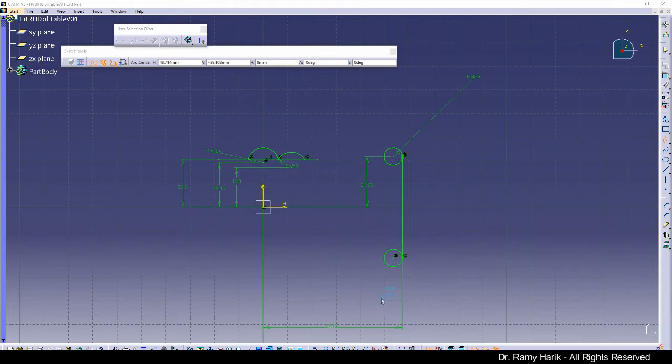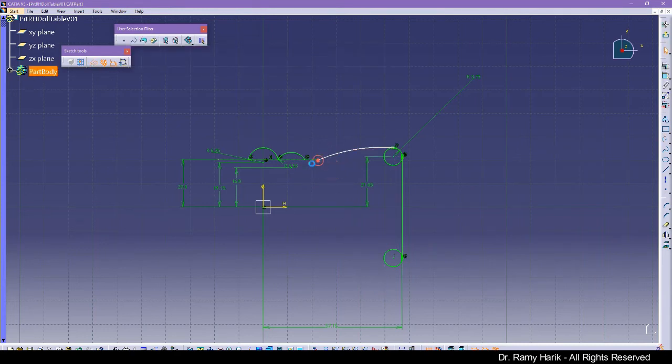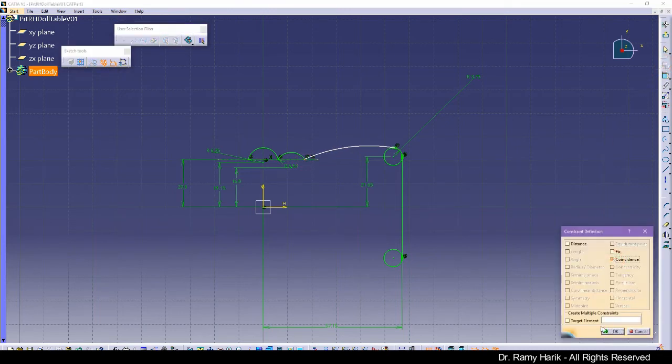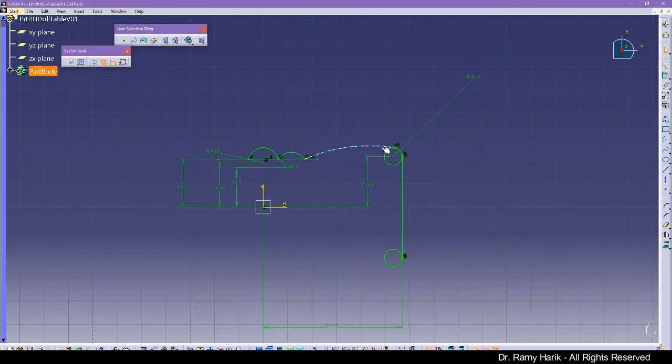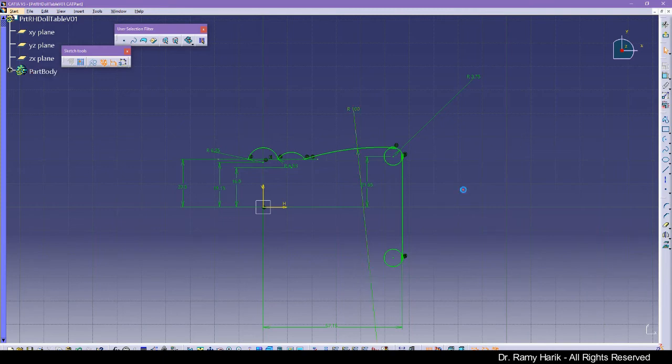So somewhere here, the center, we're going to go with this arc. So let's remove the construction element, and we're gonna have some tangency going, and it's going to connect to this point. So I'm gonna just put randomly here a point, and then we're gonna say this one and this one, there is a coincidence, so that is good. And then the tangency in here, the coincidence in here, and then we are going to put the dimension radius of 100. Hopefully that will be okay. Here we go, that's perfect. Some quick trim on this circle here, and we got this right.